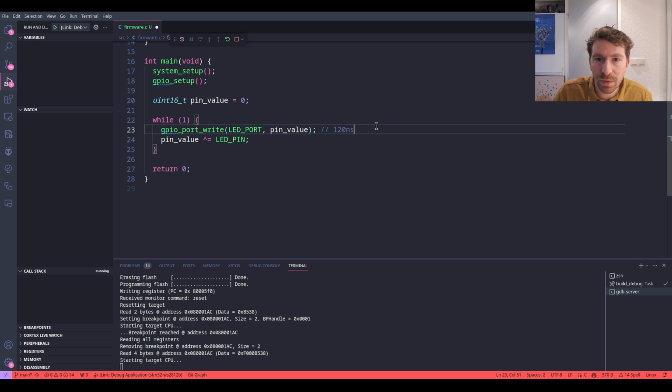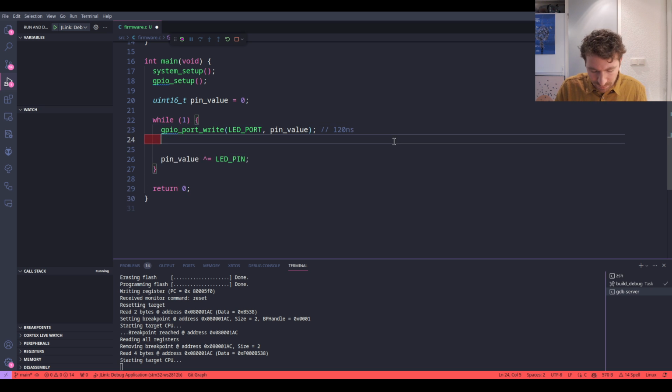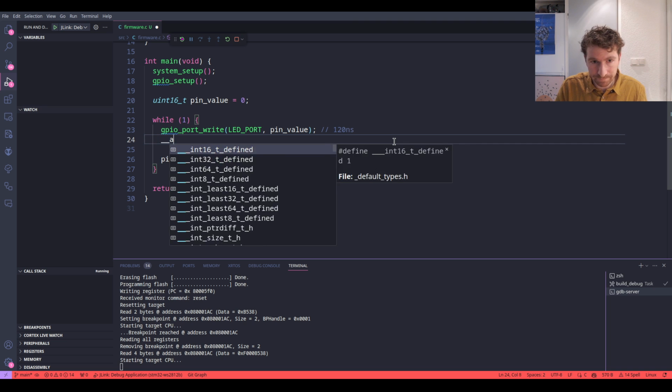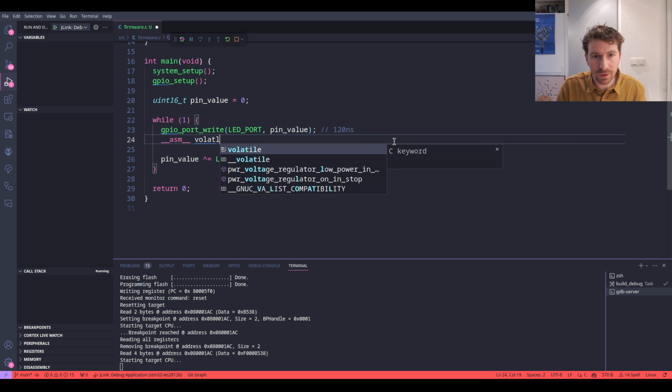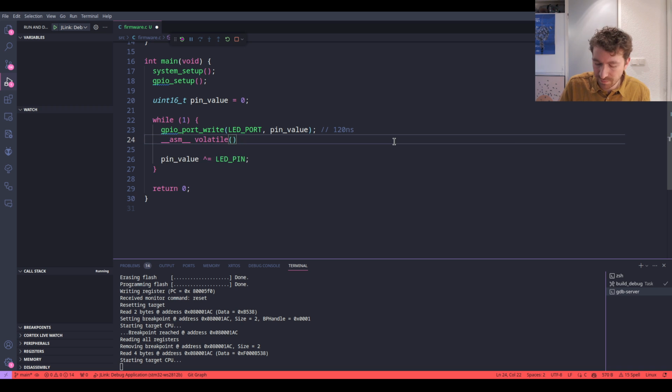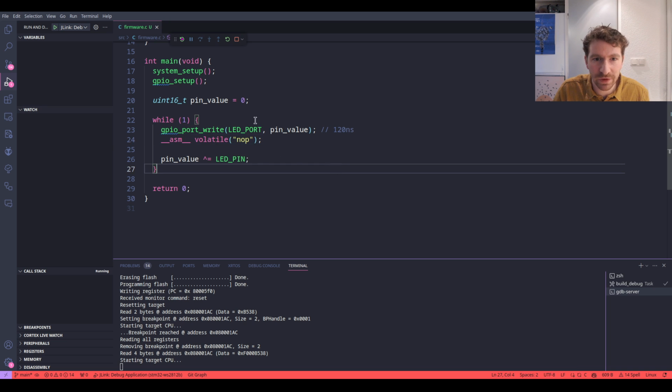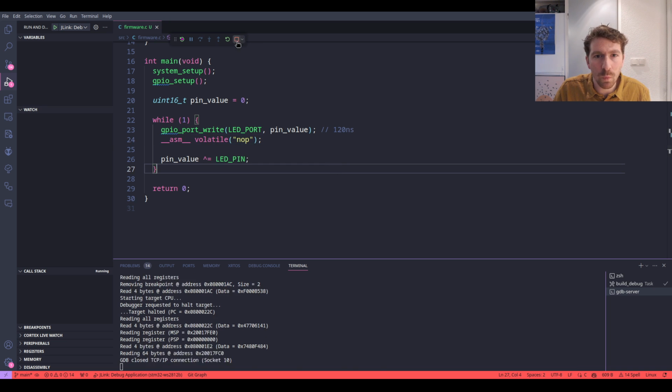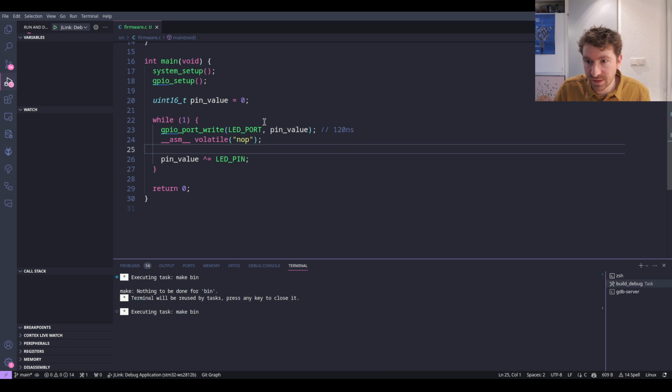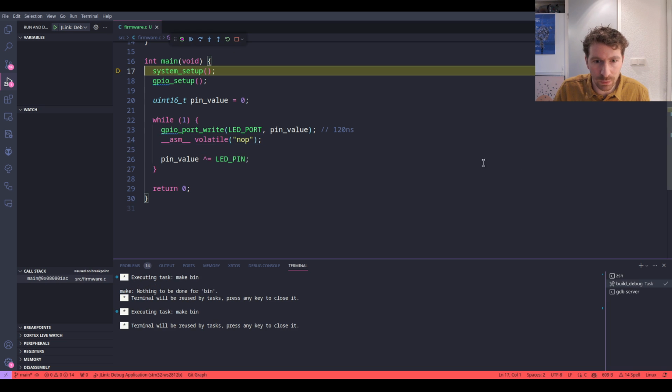Okay, so what we're going to do is insert no-op instructions instead. So what I'm going to do is just use ASM volatile, so tell it to insert some assembly, tell it not to remove it by putting the volatile in there. And so let's just put one no-op instruction in, and let's see where we get from that. So we've got a no-op in there.